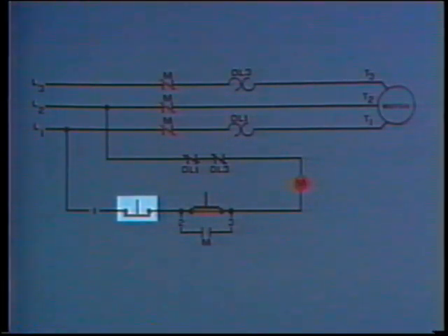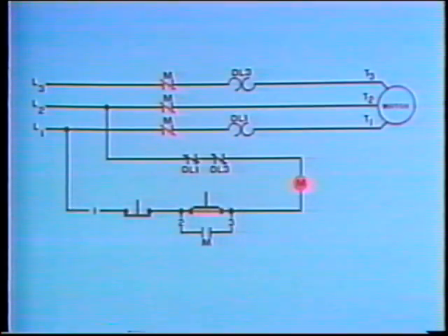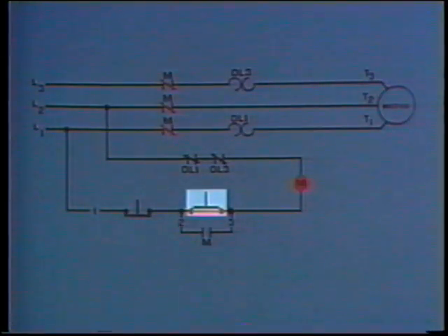He can eliminate the operating coil because the main contacts in the motor circuit are closing. If the operating coil were malfunctioning, the main contacts would not close and the motor would not run. If the stop button was the problem, current would not reach the magnetic contactor's operating coil and the motor would not start. The only components left that could malfunction are the start button and the maintaining contact. There could also be an open in the wires leading to the maintaining contact.